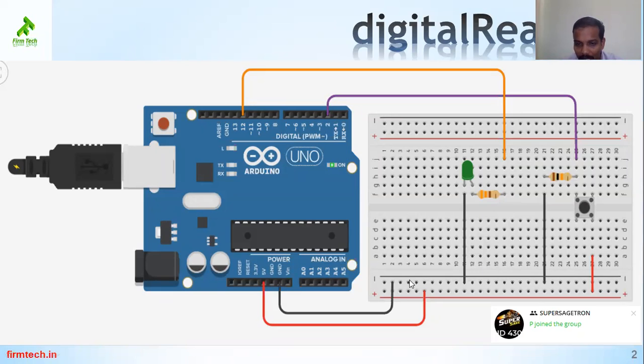See here, all these 30 points will have negative, that is ground, that is 0 volt. So I have connected this LED cathode to this ground via this point, and there is no change in this. The anode of the LED is connected to pin number 12 through a resistor, the same resistor.